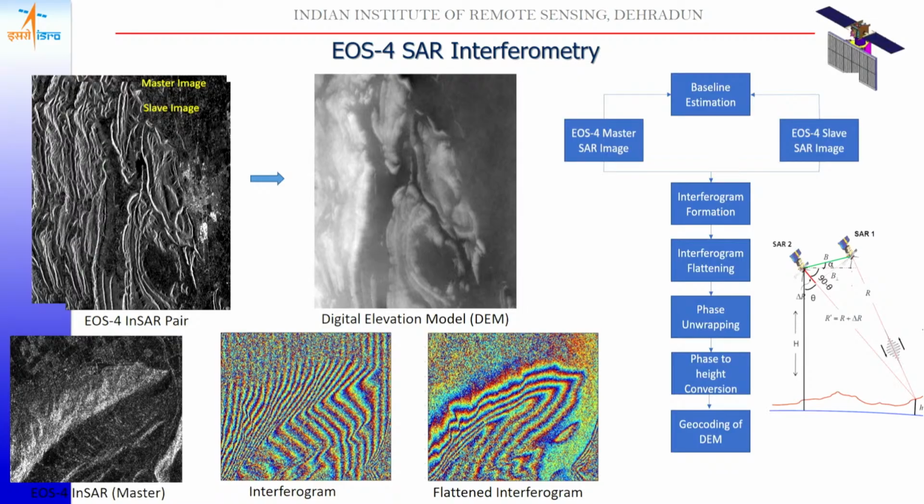If we want to do the interpretation in the SAR image, we can have one optical reference image, and with respect to that we can see which objects give higher backscatter or lower backscatter, and what the different SAR sensors available globally are, so that you can utilize them for your application: what resolution you want, what polarization you want, which look angle you want, and what type of system is preferable for ordering the data for your particular application.